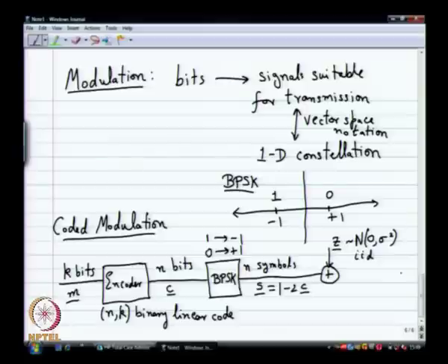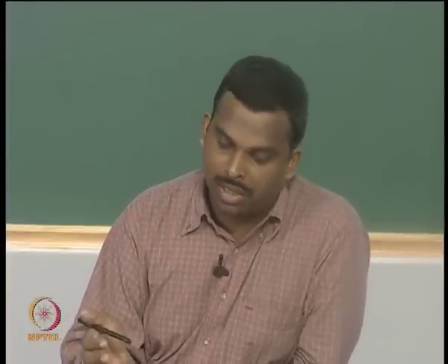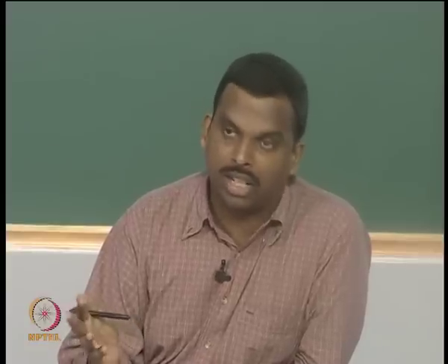There is a very rigorous justification for it. You can start from a set of signals, let us say 2 signals, express them in terms of a basis like this, and then send that signal out and assume some n of t gets added to it, and then you design an optimal front end which is called the matched filter. You design that, and then you look at a sufficient statistic which will be just this, some noise vector being added to the representation of the signal in the vector space notation.